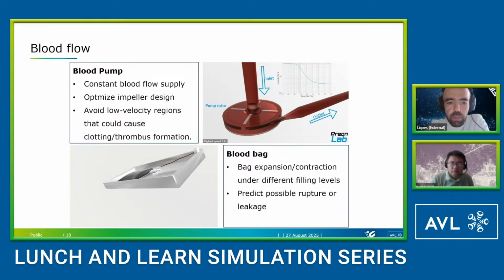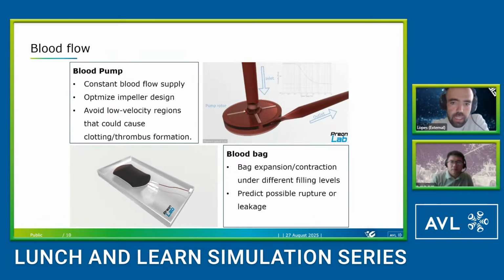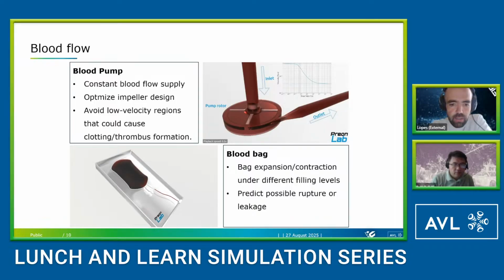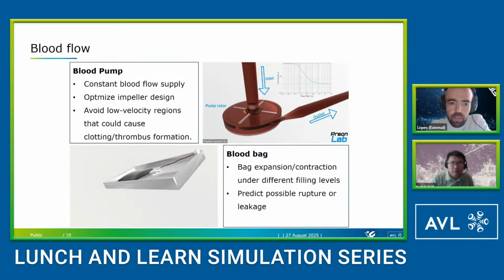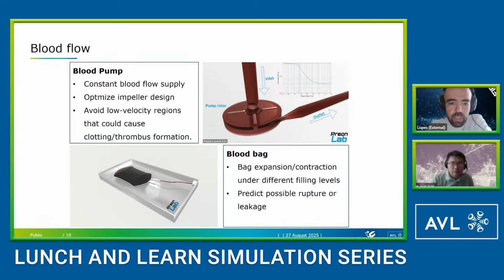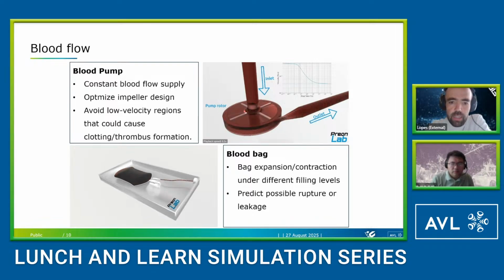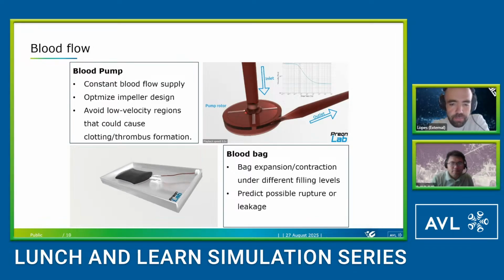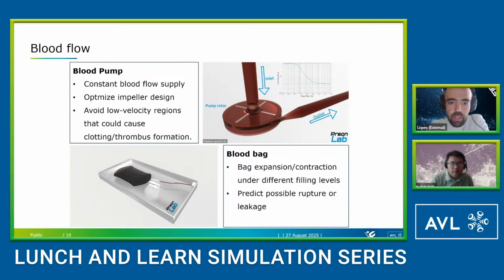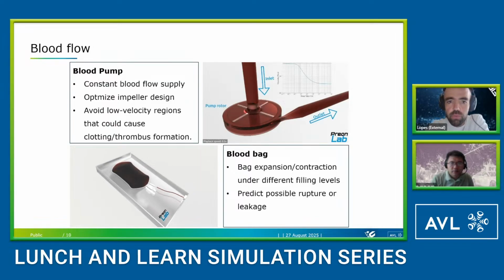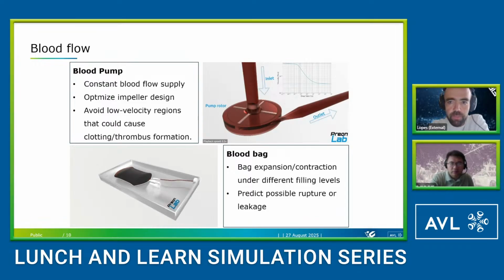In this simulation, we wanted to showcase basically the behavior of the bag. And in a simulation like this, you can get insights into the forces and the stresses on the bag and possibly look out for rupture or leakage at some points. And as I mentioned again, Carreau-Yasuda was the proper model to simulate blood flow.